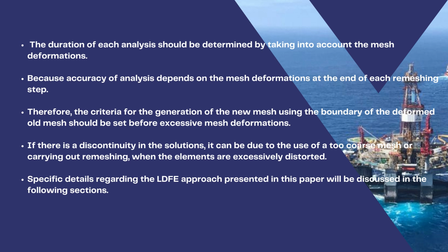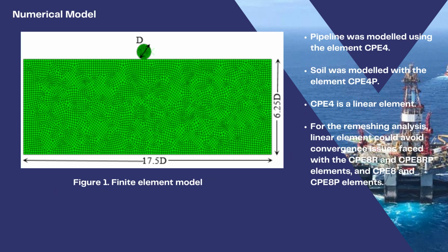If there is a discontinuity in the solutions, it can be due to the use of too coarse mesh or carrying out remeshing when the elements are excessively distorted. Specific details using this approach is presented in the paper, and you can refer to the paper for more details.